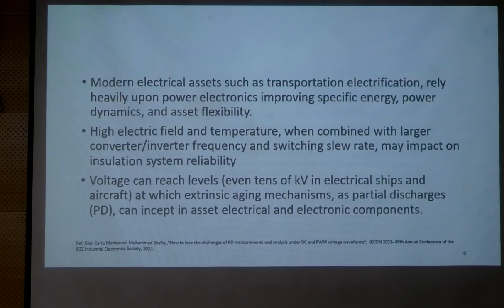So high electric field and temperature, when combined with larger converter or inverter frequency and switching rate rises, will certainly impact the stress in the insulation system. So that affects the reliability of the machines.